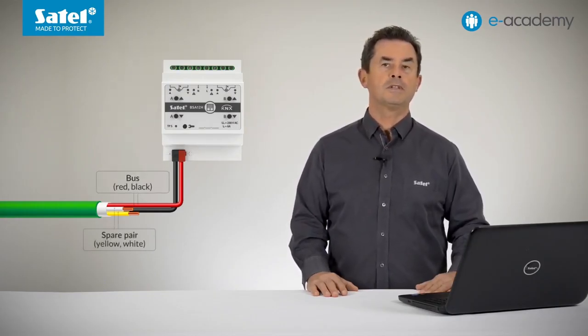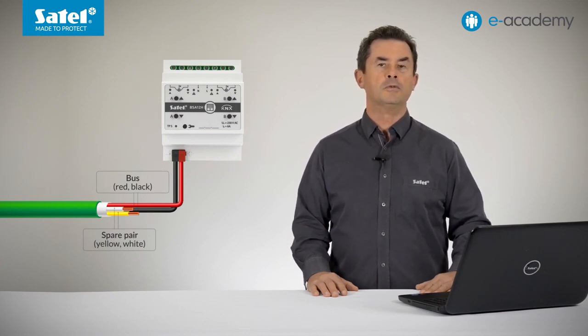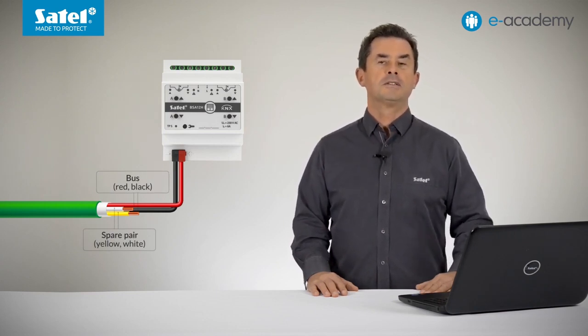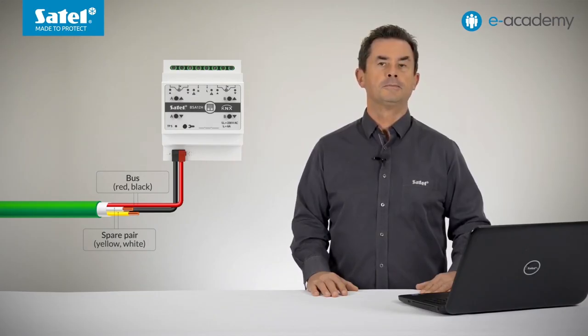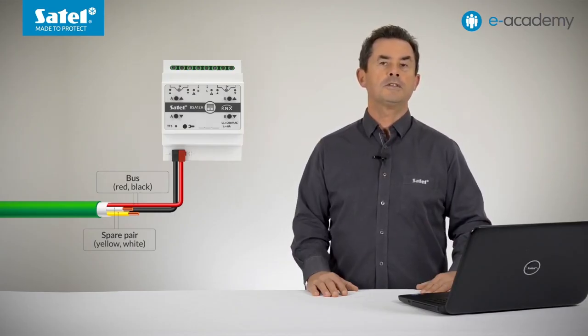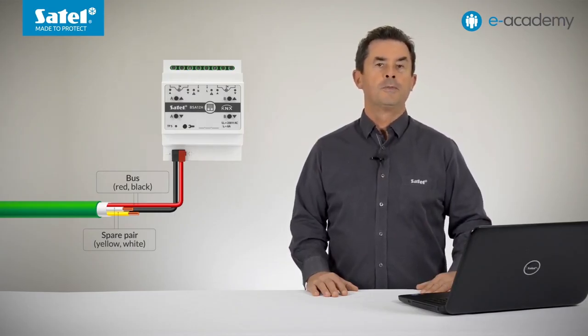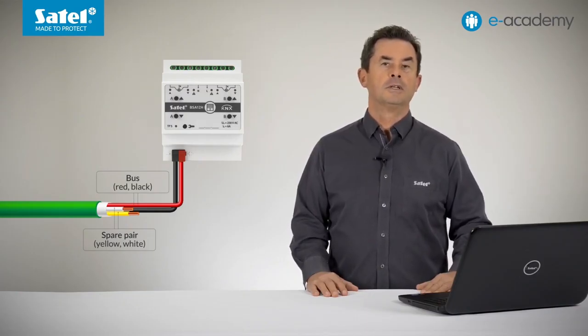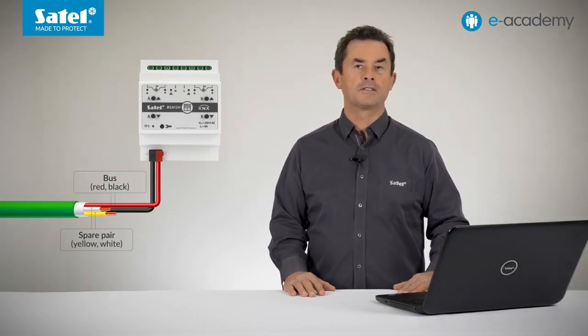They are sometimes used, for example, to connect the power supply to modules, using 24 volts DC. Both pairs are twisted together and housed in a metallic shield. The color of such a cable's outer insulation is green. This makes the bus cables easier to find in the clutter of building installations. Certified cables are marked with the KNX logo.